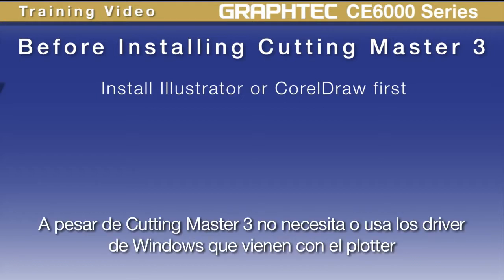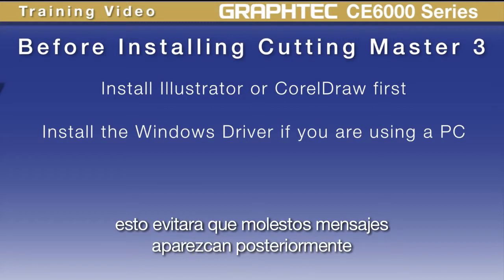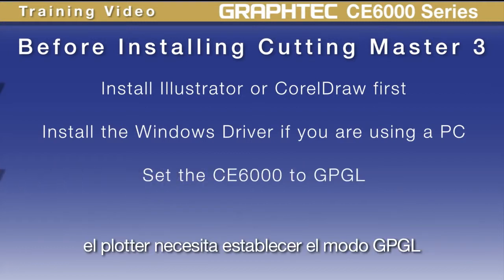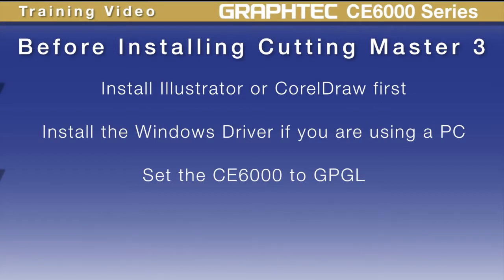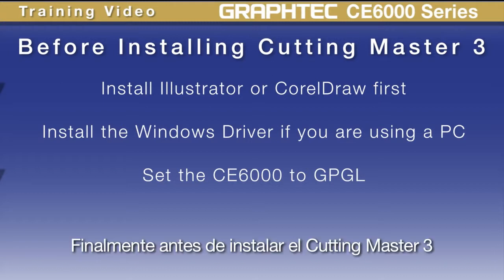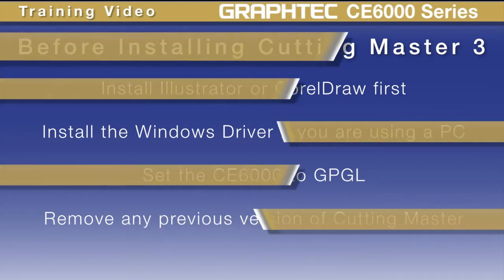While Cutting Master 3 doesn't need or use the Windows drivers that came with your cutter, it is always a good idea to install the drivers. This eliminates annoying plug-and-play messages appearing later on. Since Cutting Master 3 outputs to Graphtec's cutter language, known as GPGL, the cutter will need to be set to GPGL mode. This was covered in the installation and setup lesson of this video. If you're not sure how to do this, review that lesson or look in your manual. Finally, prior to installing Cutting Master 3, remove any previous versions of Cutting Master 2 or Cutting Master 3.